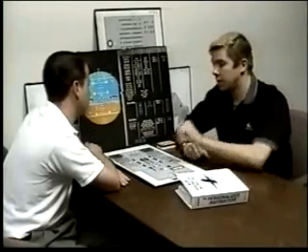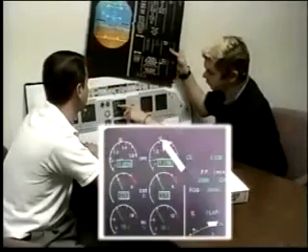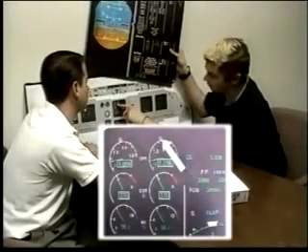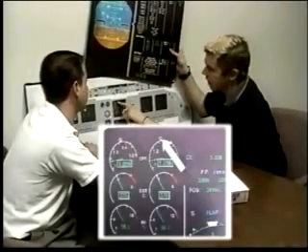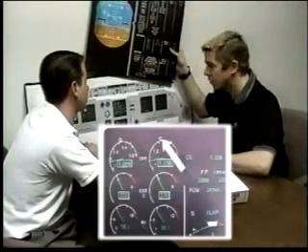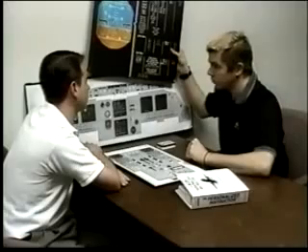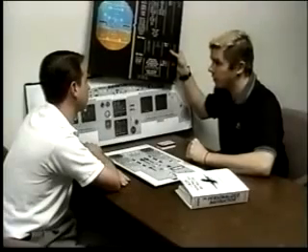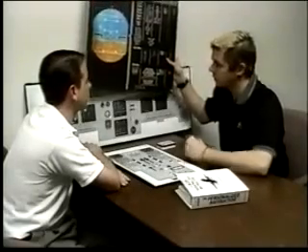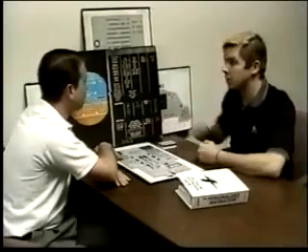How would you get rid of thrust lock then? Well, it's going to be up there flashing and dinging until you move the thrust levers. The second you move the thrust levers, the thrust is going to try to match what the TLAs are. So the technique is to read what EPR you have, in this case 1.056, and then move the thrust levers back to match that EPR. The thought being that if I was stabilized at 1.056 before and it's stable now, it's going to be stable for me when I get there. So I bring the thrust levers back and match the EPR to the TLA, or the TLA to the EPR.